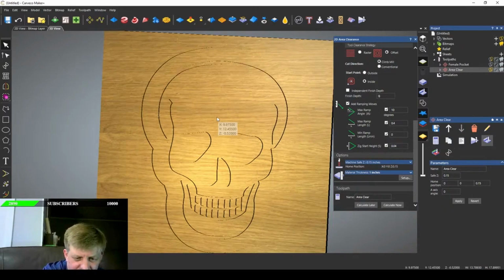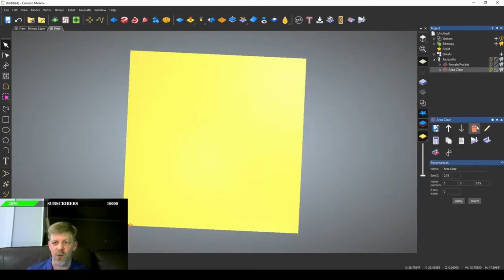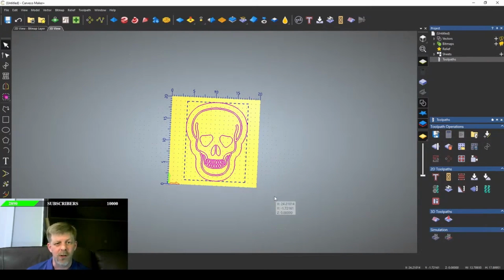Do we have any questions so far? Again, the situation depends on how complex your inlay is going to be. These two examples that I just showed you are basic inlays. It's the best way to start doing inlays. With basic inlays, it's hard to mess up these end mills. When you get into the V-carve inlays, it's a little more complicated, and there's a little more trickiness that has to go on to get that to work. But you can accomplish a lot smoother or better details with a V-carve inlay. And we'll go over that now. So I just wanted to show y'all basics of how to do a basic inlay using just end mills.